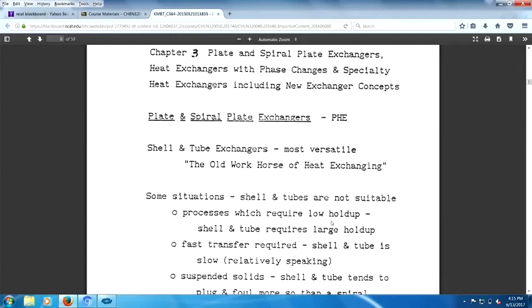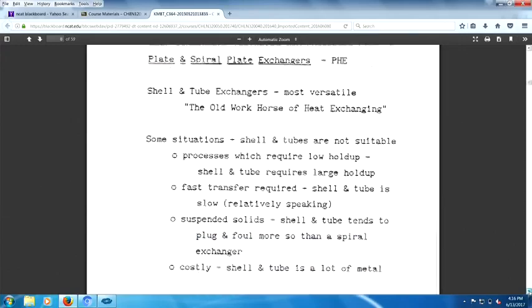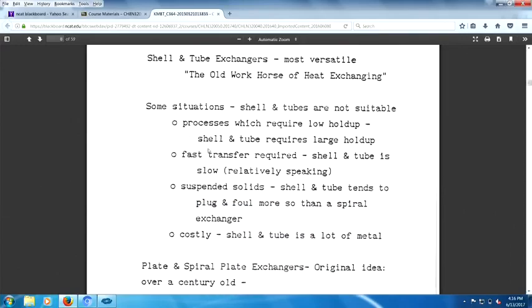Well, you consider the fact that with orange juice, you're going to heat orange juice up to evaporate off the water. But orange juice tends to be sensitive to metal. You can put orange juice in a metal cup and you will have a metal taste to the orange juice. Metal ain't a great idea with orange juice. So you want to have as little exposure as possible, right? So you don't want to heat up orange juice or have an evaporator with a shell and tube.